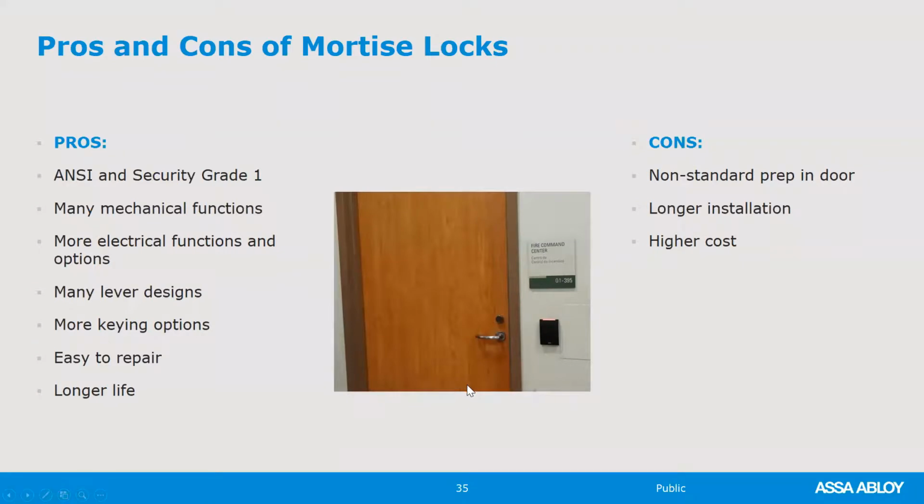Mortise locks are easy to repair. You can keep spare parts, and your locksmith shop can repair them as necessary, and they have a longer life. More often than not, they have better cycle testing to exceed ANSI grade 1. They're heavier duty and more durable.